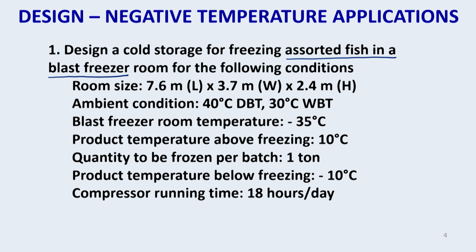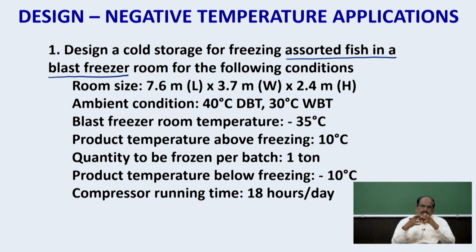The second design in this part 1 of the lecture is that I will be designing the cold storage for a plate freezer. The difference between a blast freezer and a plate freezer is that in a plate freezer, the cold plate will be in direct contact with the product for achieving the cooling process, whereas in a blast freezer, cold air with high velocity will be circulated.